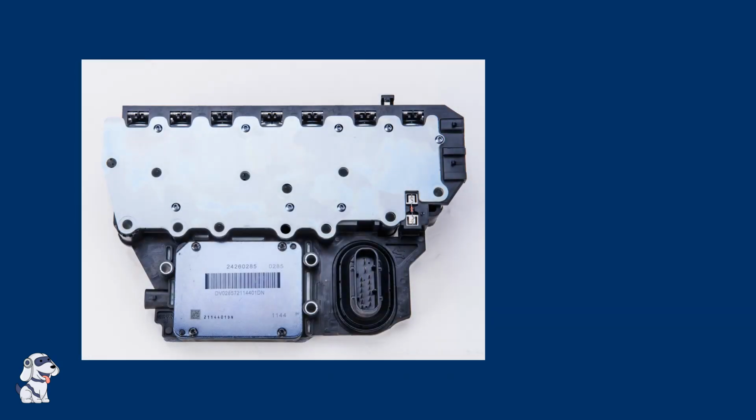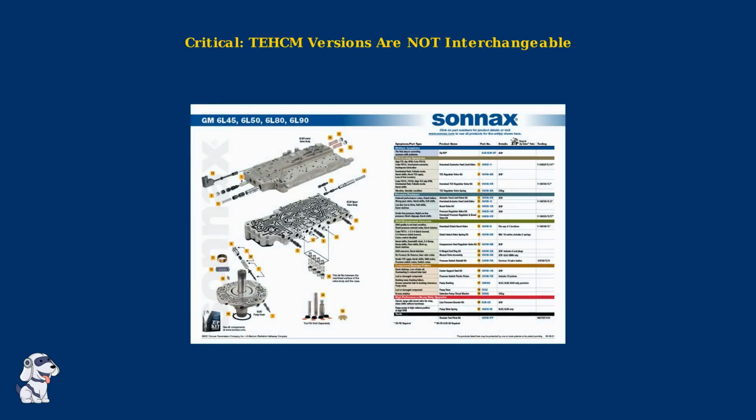At the heart of this transmission's control system is the TEHCM, the Transmission Electro-Hydraulic Control Module. This critical component houses the transmission control module and manages all hydraulic functions through electrical signals. Here's where it gets complex. Different versions of the TEHCM exist for the same 6L80 transmission. These variations have different part numbers and limited interchangeability, making proper identification crucial for repair success.